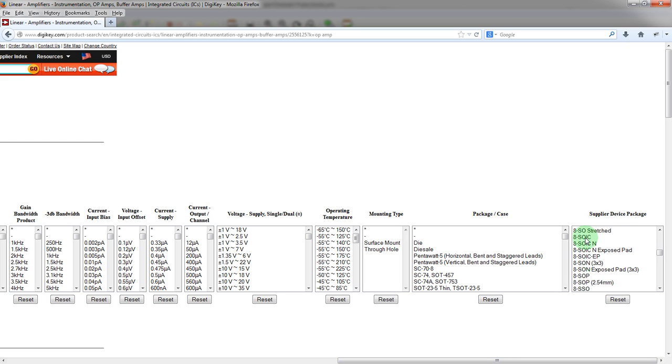So an 8 SOIC, you're going to have a lot of results there. But an 8 SON or 8 SON exposed pad, as you move into some more of these, you're going to find less and less commonality among them, especially with pinouts. And sometimes it's advantageous to the vendors to actually have different pinouts, because then you design in their chip, maybe you like 1 or 2 specs of it, but then you design in their custom footprint, and then you're kind of stuck with them. I don't think it's necessarily malicious, but I think it is based on patent portfolios and sometimes also characteristics of the circuits for isolation or other things there.